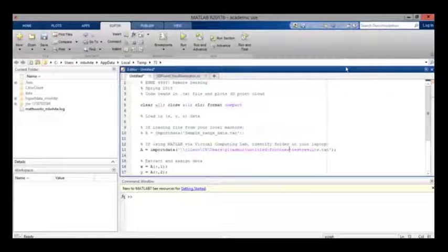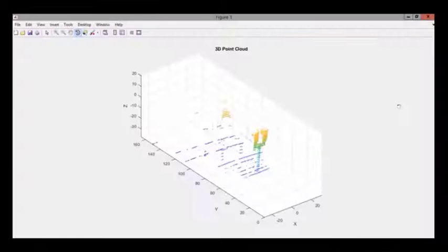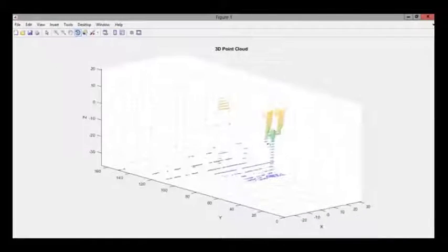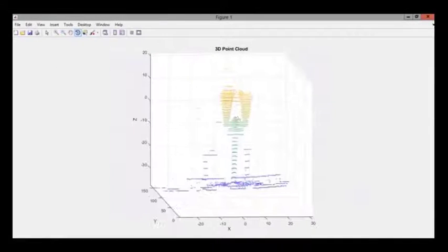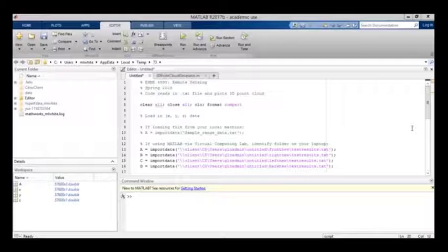All right, so we've taken all our data from Python and we now have it in MATLAB. We're going to take the front new data text file that we created and assign it to X, Y, Z variables. So X is the first, Y is the second, and Z is the third. Then we'll plot it as a point cloud. So here's our image of the point cloud. We can clearly see the front of the parking meter, some of the features like the tapered edges, the rounded sides, the sign, and the circular shaft coming up.